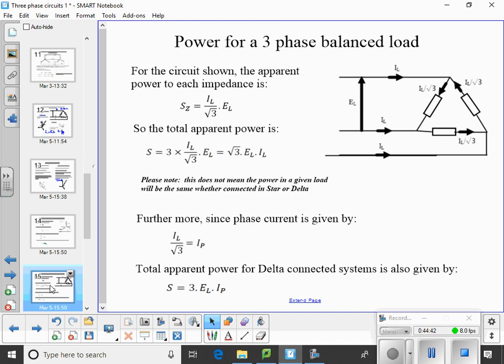So we have delta for the main transmission, and we use that with delta connected motors as well, but usually delta loads are where you have a nicely balanced load. Whereas a star system allows for imbalance by having the neutral conductor. So you're all right connecting your motor without a star neutral connection because that's generally balanced, but multiple loads won't be.